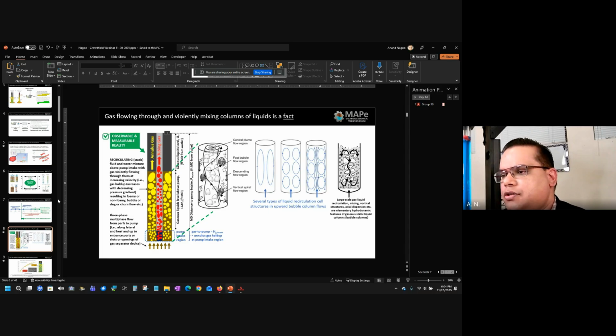You've got four forces, right? You've got your convective inertial force, your viscous force, your buoyancy force, and the interfacial tension forces. So you need to actually have enough momentum, enough well energy, to cause the liquids rate to become a positive liquids rate, to rise. Otherwise, just a change in diameter, which your velocity string in a static liquid column is, will act just as a capillary string or just as a straw in your glass full of water. Okay.